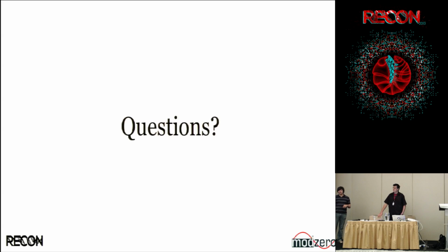Everything terminated design. Okay. It means that the buffers need to be able to handle some negative signals and generate them. Is that possible? No, but you can completely disable the buffers. You can bridge them. You can pretend they're not there. This is completely doable. So if you want to implement your own termination scheme, do custom I/O, LVDS using crazy $10 chips from TI doing SerDes and then trying to read it back as fast as you can, you could try this. There's no reason it shouldn't work. It's just that this is not something the board can do as is. You would have to build some custom hardware to go with the board.